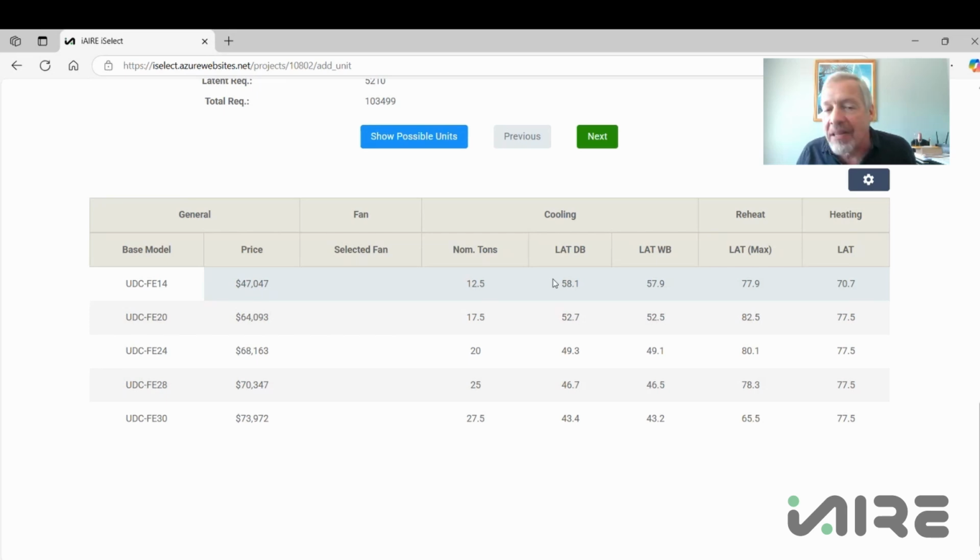And I can't ship it that way because now it's too big. Once I go to a chassis 6, I bolt the ERV onto the end of the unit and I can fit it back onto a flatbed. The smaller units, chassis 4, 3, 2, 1, will fit on a flatbed even in the L shape. So that's why a 15 ton is not coming up in this particular selection.